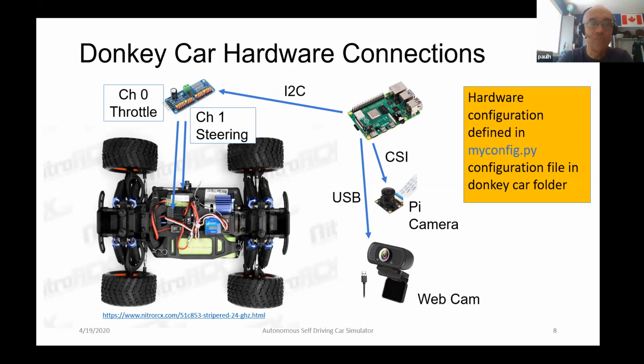Another issue people will get is mixing up channel 0 and 1. When you're calibrating or testing the signals, you have to figure out which channel is connected to which of those. Obviously, it won't work at all if you've got them backwards. But you can either switch them through the hardware, switching the wires, or you can also switch them in the hardware configuration.